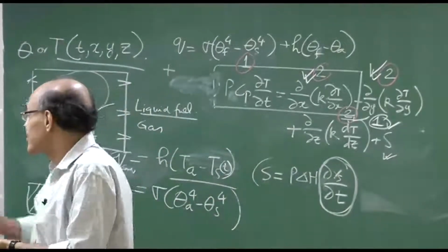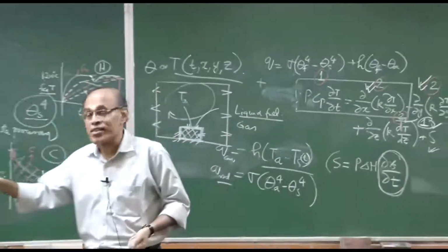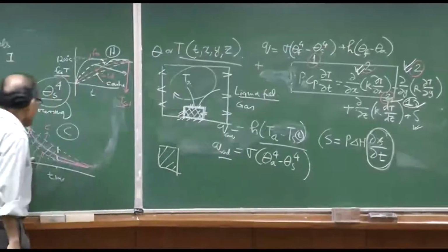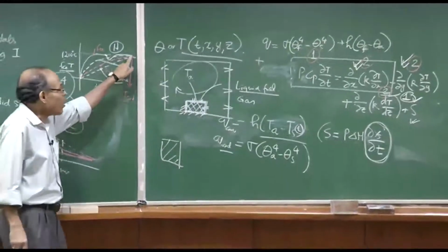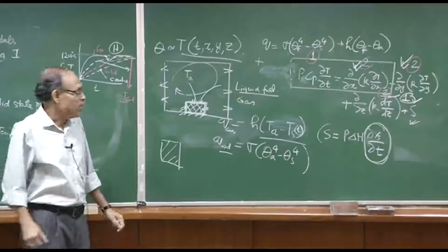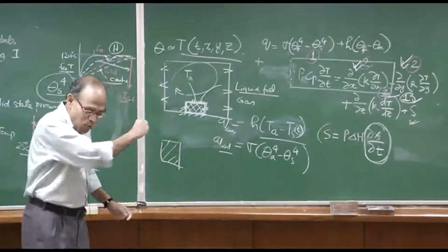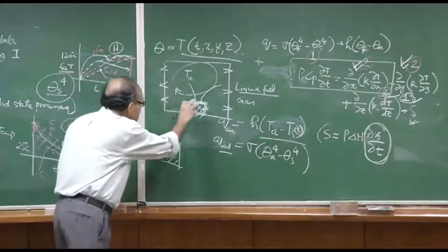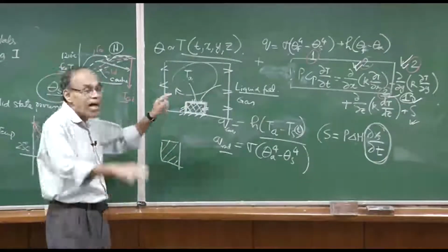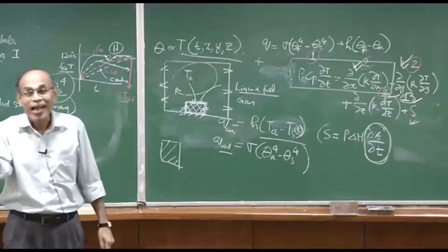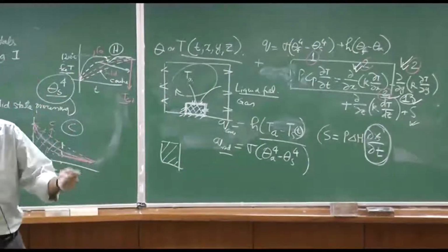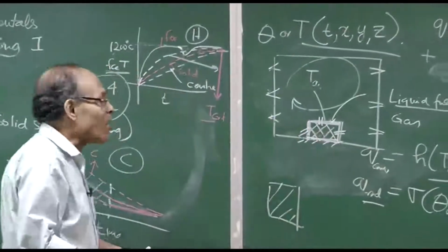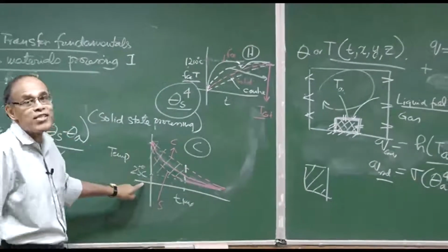For example, I will discuss in the next class the furnace cooling operation, and that essentially means that after the ingot has attained a steady state temperature, you do not want to bring it outside and cool it in the ambient. You want to keep it inside the furnace, shut off the furnace, and then let it cool down. You know the operations, annealing versus normalizing. Normalizing essentially means air cooling. So, you take out the ingot after homogenization, and that is what we have discussed today.